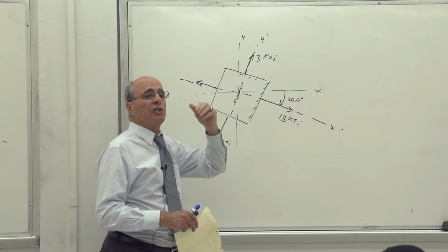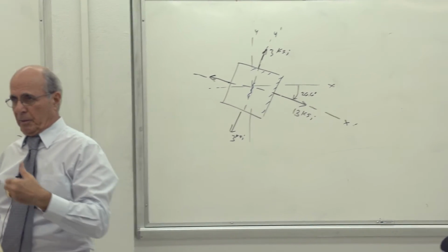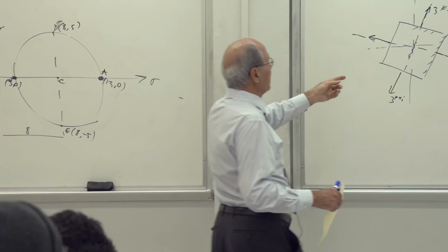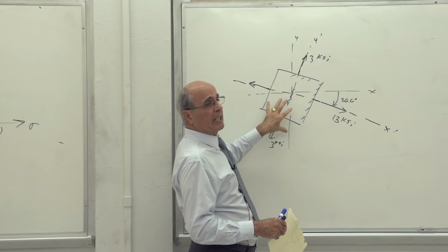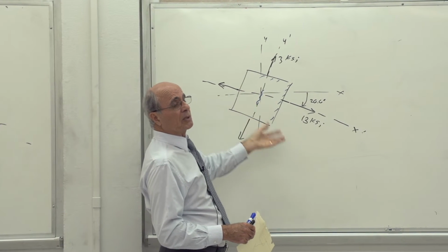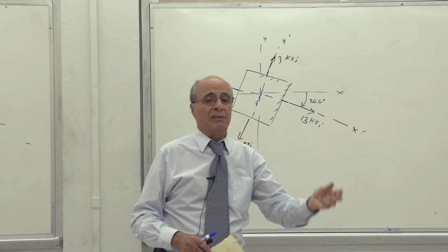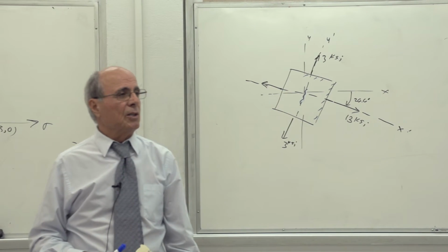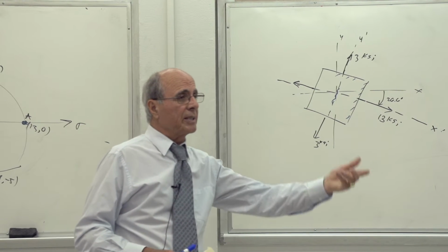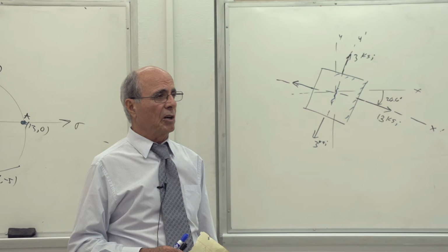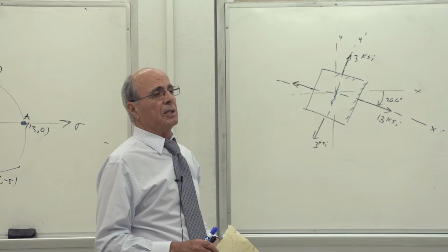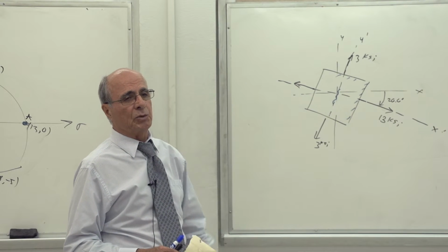So the strain gauge shows you the effect. If there is slightly a crack here, the strength of the material becomes less, the stresses become larger. As the result, the strain becomes larger. Remember the strain epsilon and gamma, is that understood? Then the red light comes on in the cockpit, so the captain has to stop the airplane.